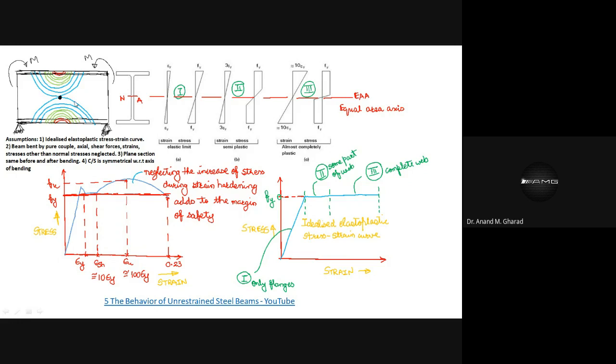Okay, this is going to break. Or over here you can expect the formation of neck. So in other words, this is known as plastic hinge. Okay, plastic hinge. Why? Because see, what the scientists have done, they have idealized this stress strain curve, and what they have termed this to be the plastic line or elastoplastic behavior. And therefore the hinge which is associated to this failure type is known as plastic hinge.